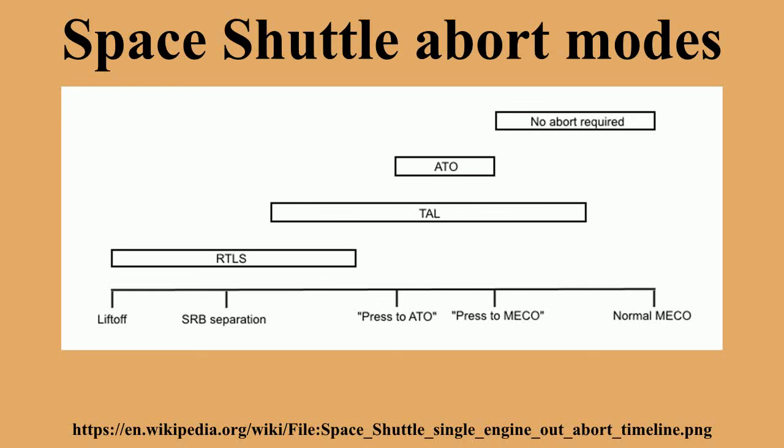A particularly significant enhancement was bailout capability. Unlike the ejection seat in a fighter plane, the shuttle had an in-flight crew escape system. The vehicle was put in a stable glide on autopilot, the hatch was blown, and the crew slid out a pole to clear the orbiter's left wing. They would then parachute to Earth or the sea. While this at first appeared only usable under rare conditions, there were many failure modes where reaching an emergency landing site was not possible, yet the vehicle was still intact and under control.